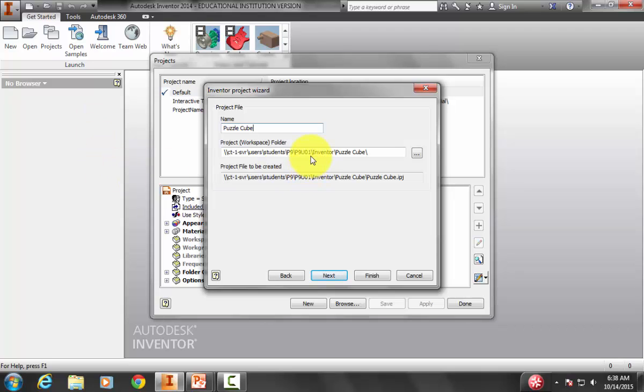So what you're going to do is select everything to the left of the backslash that's to the left of the word Inventor. So I'm going to illustrate it right here. See, I missed it. I missed the one. So I'm going to select all of that. So everything to the left of the backslash that is to the left of the word Inventor. That word Inventor represents a folder called Inventor, and you're just going to replace that with Z:. That's our virtual drive,